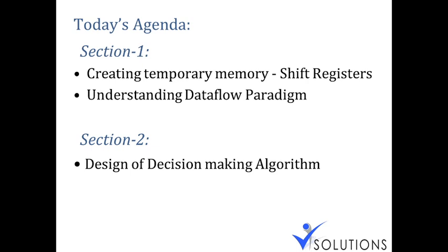Finishing all these basics, we moved directly into loops. We saw there are 2 different types of loops: for loop and while loop. For loop is a finite loop, where we mention how many times the loop is supposed to execute. Coming back to the while loop, you have a condition terminal where you control it using boolean data. It need not always be a control from the front panel. It can be a programmatically calculated value. Yesterday I showed you an example where we compared marks: if it is more than 40, it is on or off, something like that. We can try designing an application.